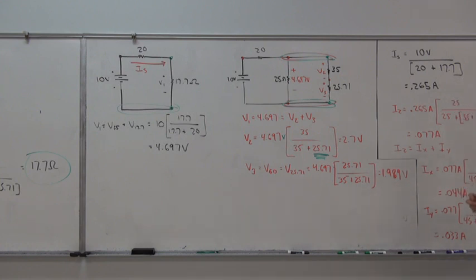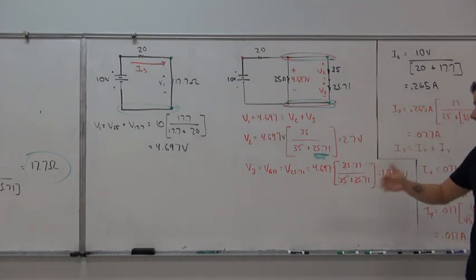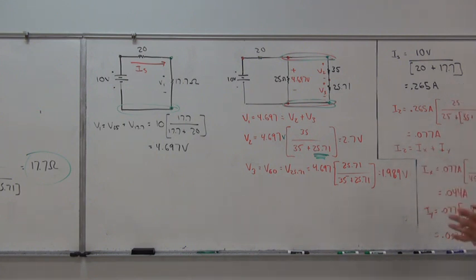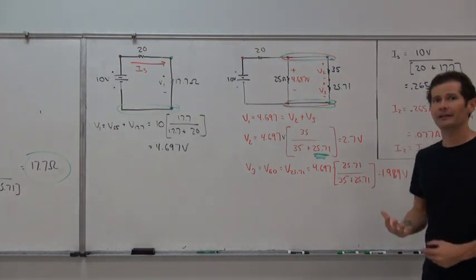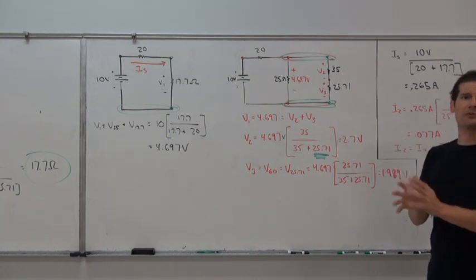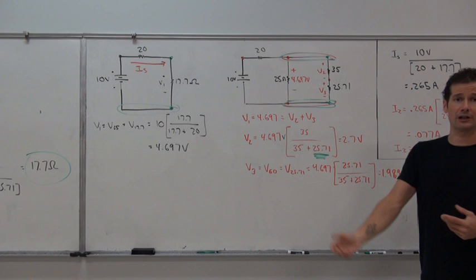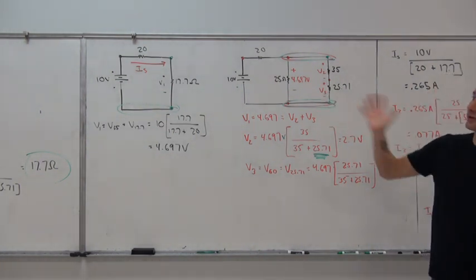Now, again, these are very, very simple. This one was actually a 3-loop circuit, but if we made a 5-loop circuit, we could still perform these divisions very, very simplistically. It's just really understanding KVL and KCL and knowing the relationships of those elements, applying the principles of those relationships, and then utilizing the tools that we have, such as voltage division and current division, appropriately.